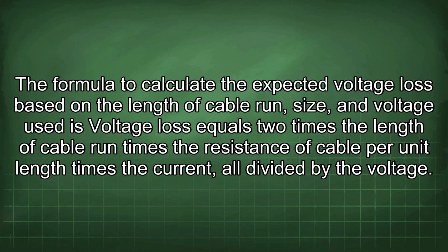The formula to calculate the expected voltage loss based on the length of cable run, size, and voltage used is: voltage loss equals 2 times the length of cable run times the resistance of cable per unit length times the current, all divided by the voltage.